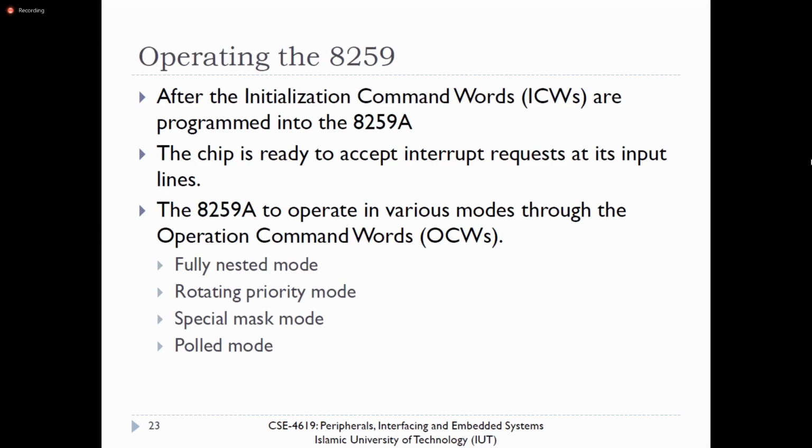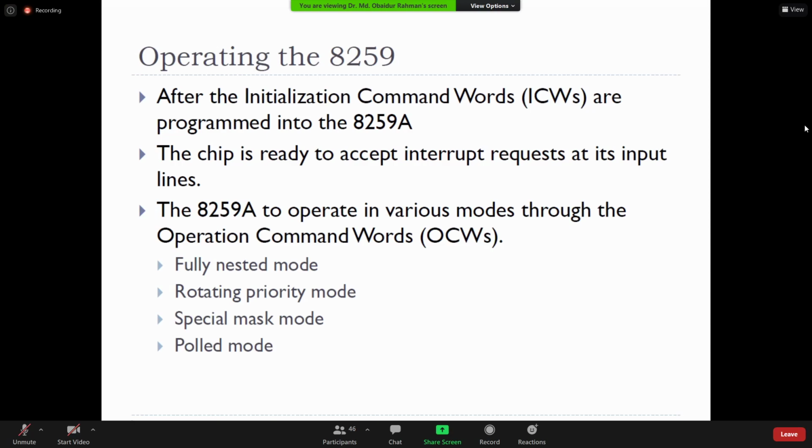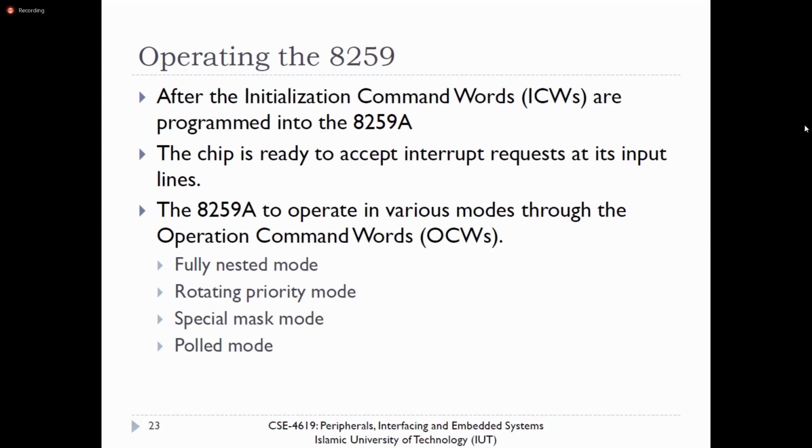Okay, this is the last slide of today's lecture. After the initialization, or after the command is placed into the control logic, the 8259 chip will be ready to accept interrupt requests from the peripherals, and it can work with 4 different command modes in the operational mode. One is fully nested mode.